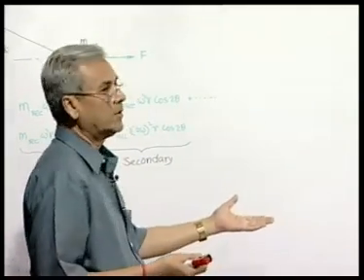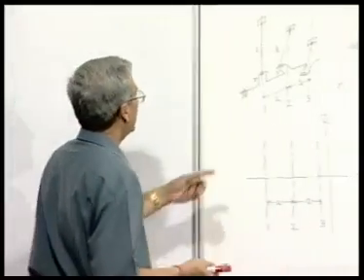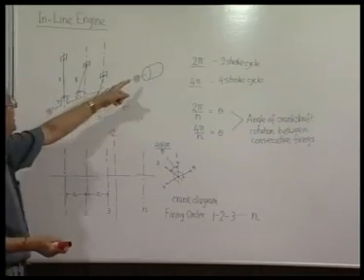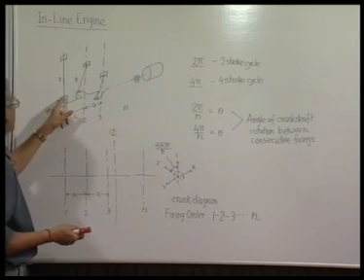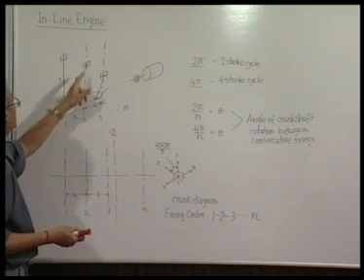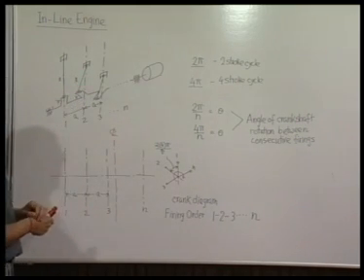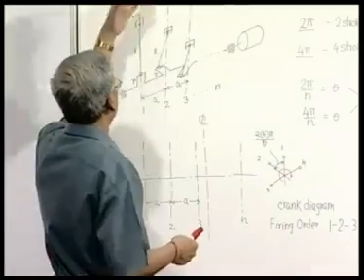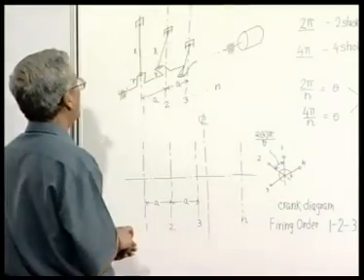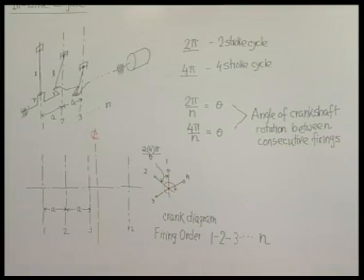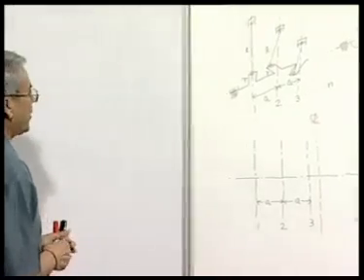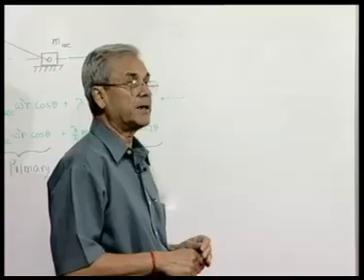Same thing here, because we have seen that the unbalanced primary force of each one can be represented by placing a mass, or the cylinder mass, here, and assuming that only the component along the cylinder center line is existing, the rest is not existing. So, somehow we are now converting our reciprocating balancing problem into a rotary balancing problem.